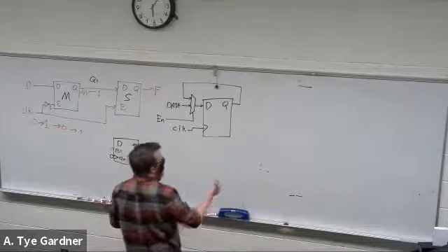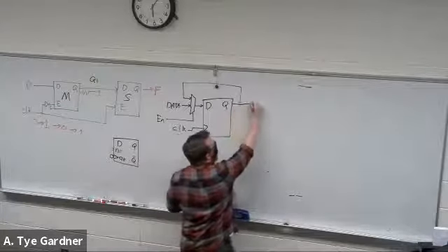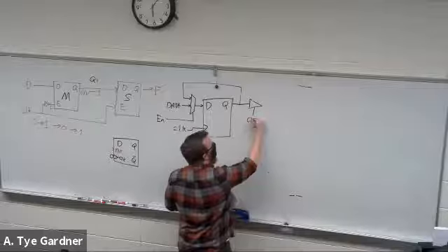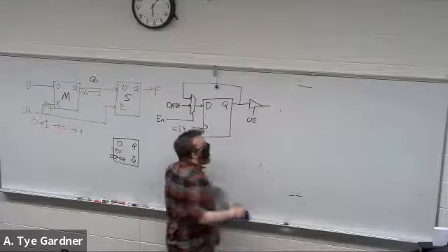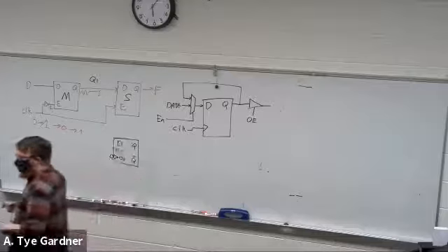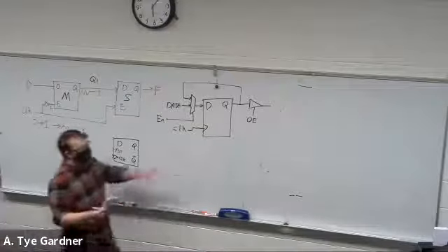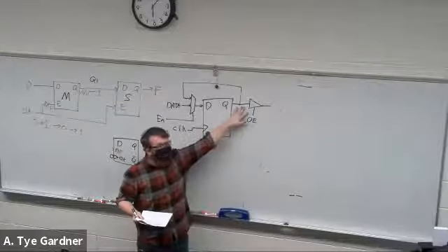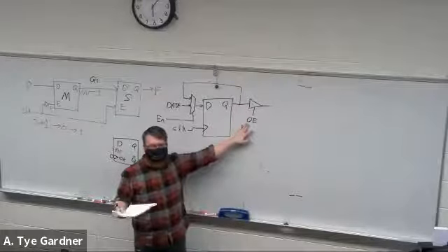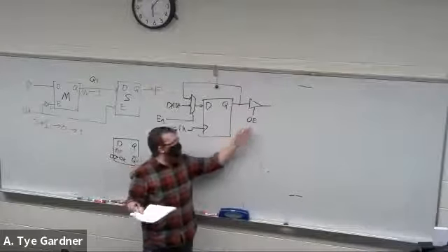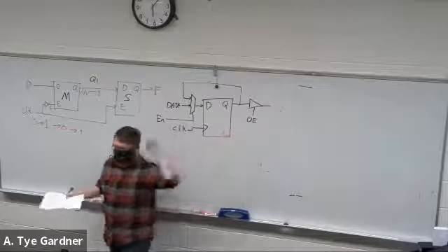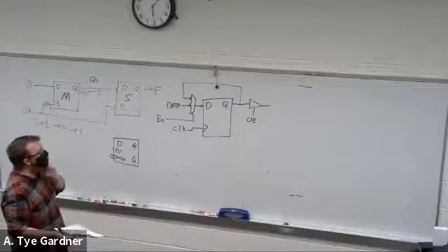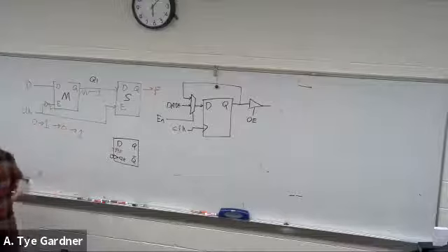There's something else that we can do to these circuits that you'll see fairly often, which we call output enable. This is just a picture of a buffer, right? It's like an inverter. But all it does is, depending on whether the output is enabled or not, it drives the signal or not. You're going to end up using this in project 3 down the line, so I want you to know it exists. We don't need much with it yet, but it's a way of saying sometimes I want it to drive a line, sometimes I don't.